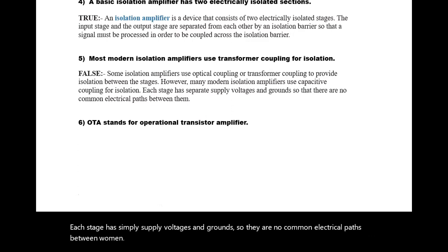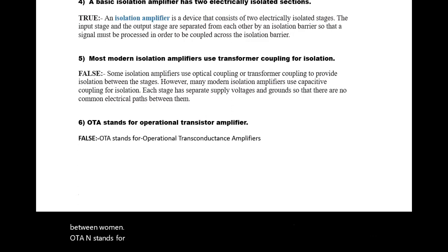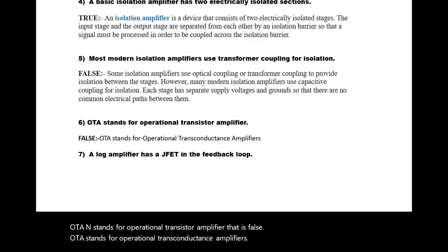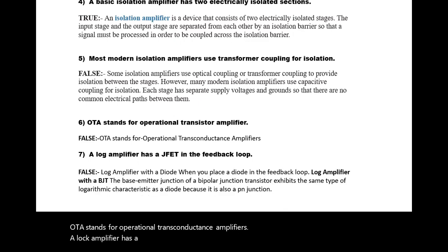Question 6. OTA stands for Operational Transistor Amplifier. That is false. OTA stands for Operational Transconductance Amplifier. Question 7. A log amplifier has a JFET in the feedback loop.